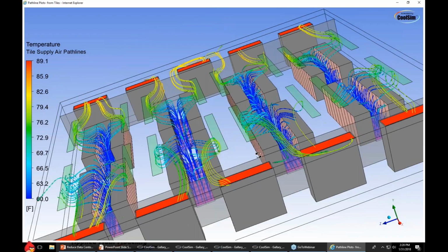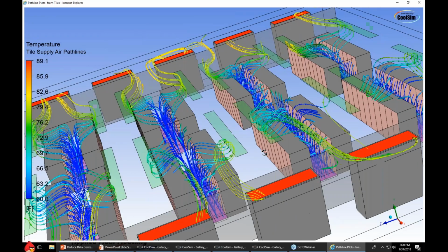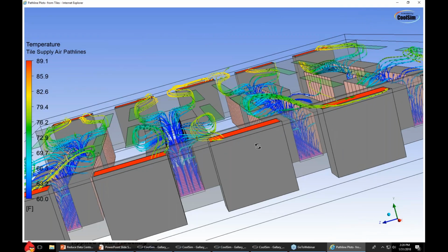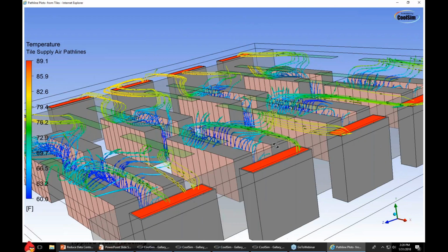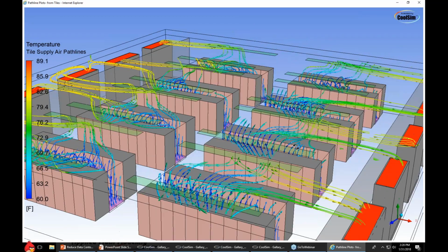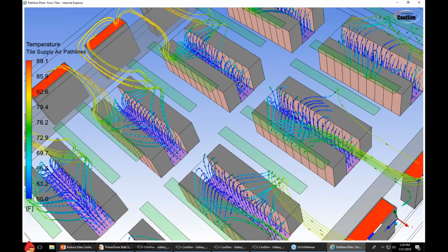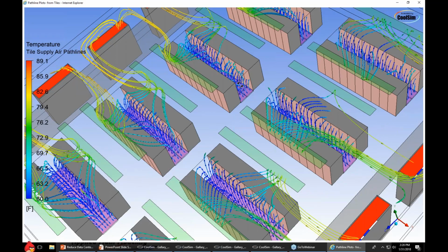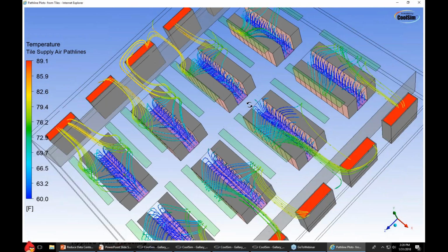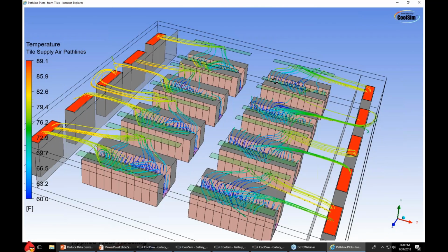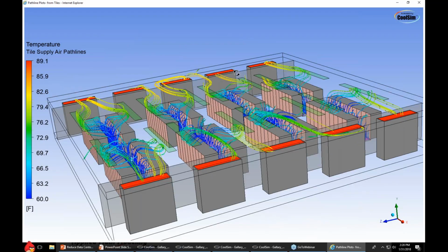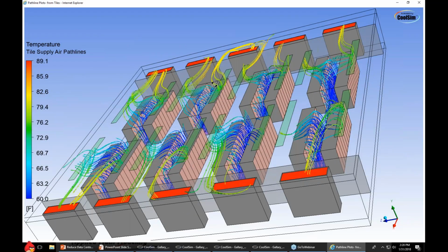And you see here that I've got air going back into the returns in the ceilings and back into the air handlers. That's supply air. You should not see any of these path lines. They should be going just like these, right to the rack and then stopping. That would be a perfect balance. But you see they're coming back in and cooling off those returns. So I'm out of balance right now with respect to that, and it is because these cracks are all running at full speed.